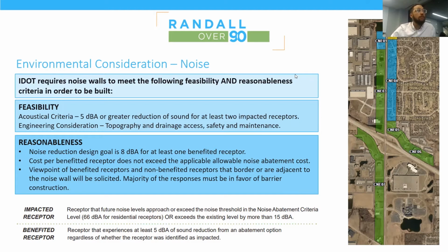Another question: have you reached any conclusions yet based on your initial work? I wouldn't say conclusions, but we have seen that existing sound levels are close to being above the noise abatement criteria that I mentioned before, which means that it's very possible that the project will have a barrier analysis.